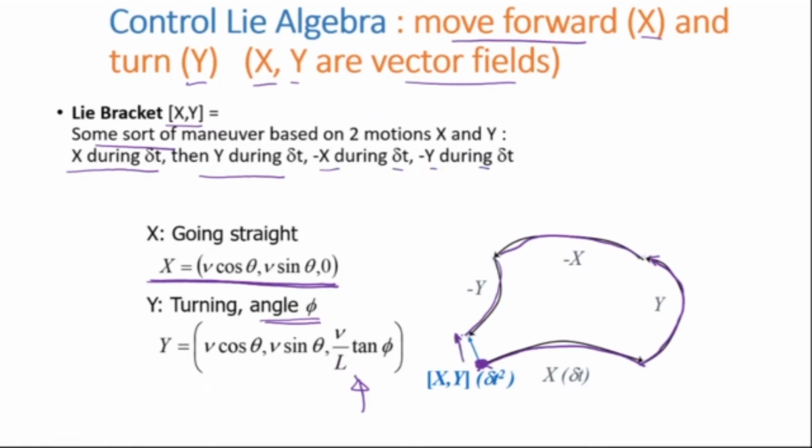So this is exactly what it is doing, and in the process it is going from here to here, which is actually sideways motion. By changing this combination, there can be different x's, right? It can go like this, like this, like this. All x's are possible. So by using different x's, it can go sideways and park in different places. That means all points here are actually controllable. So the wheel can go sideways and park anywhere.